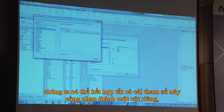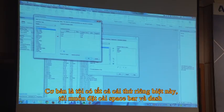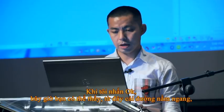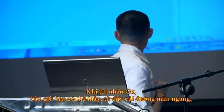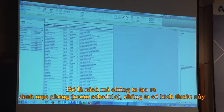All right. So for example, I want my name, which level, and what is the area in one single column. Okay. So basically I can have all these separators. Okay. That means that I want to put a space bar and a dash over here. Okay. And once I click OK, now you can see from here the level line, the resolution is a bit small, but you can see all the different parameters are going to combine into one single column. Okay, so this is how you can create the room schedules.